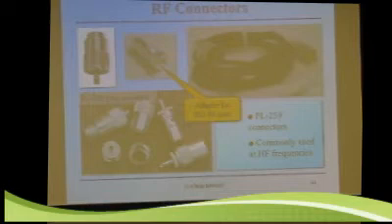RF connectors, we talked about that. Yes, PL259 was the one that I inserted the coat hanger into to make a quarter wave antenna. That's like one of these. They're commonly used, they actually are called UHF connectors, but they're almost never used at UHF.